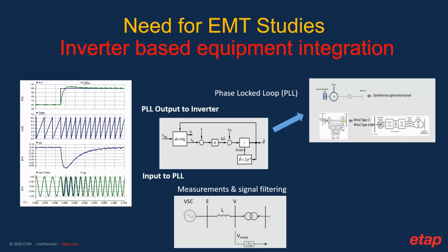There's a very specific reason for that, and I think using one or two slides, I can explain the importance of EMT studies in that situation. Now, EMT studies, EMT simulations, we said, capture the instantaneous waveform. If you have the instantaneous waveform, with some measurement or metering technique, you can estimate the angle variation of this voltage. What I mean is, if you say that the zero crossing of a voltage is your reference, then we can say the angle of the voltage will move from 0 to 360 degrees, or 0 to 2π